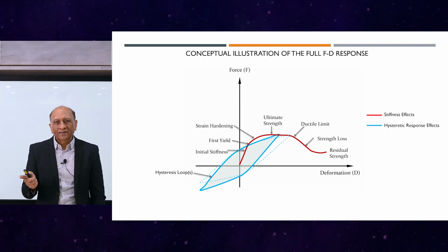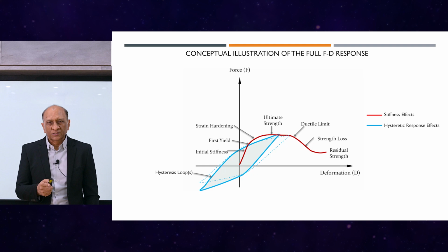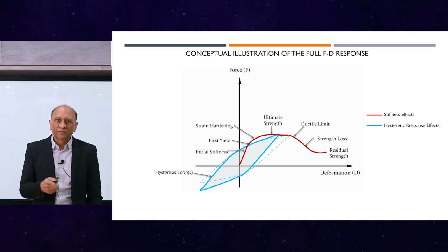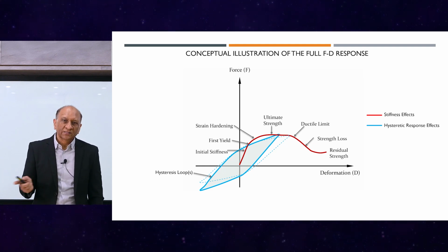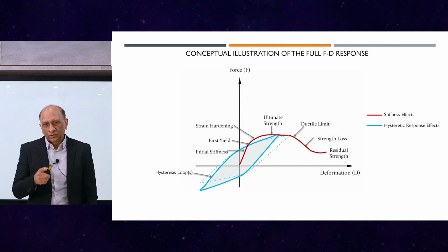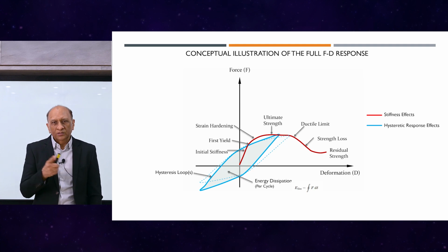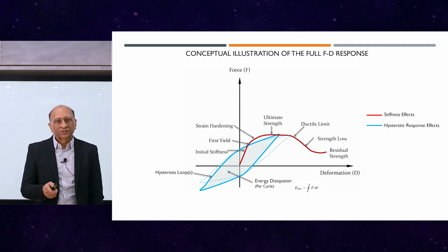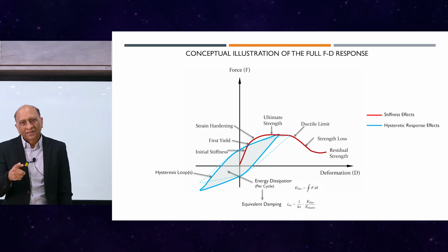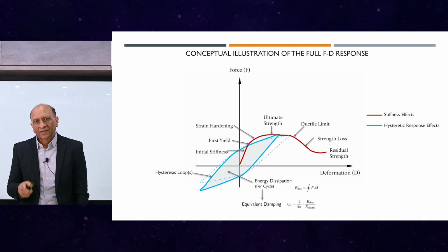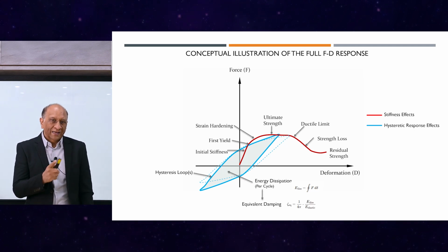And then we have the loading and unloading from the typical seismic demand. It goes up and down. It's an oscillatory motion. So we have the positive and negative loading, unloading, and increasing, decreasing demands. So we have the blue line, which is the hysteresis, and it has many loops. Each loading and unloading produces one loop, and then it can degrade the structure. It can bring that red line even further down due to degradation from the cyclic loading.